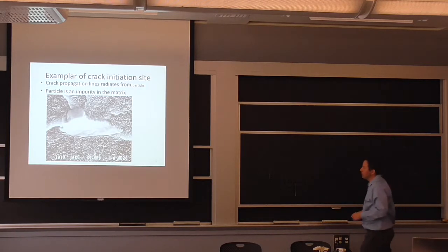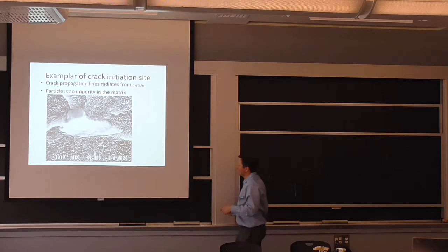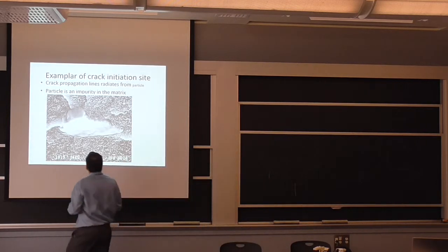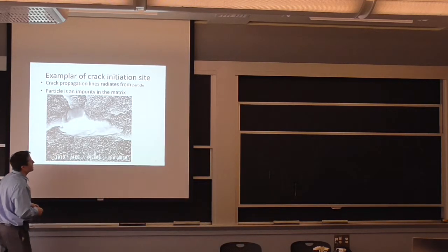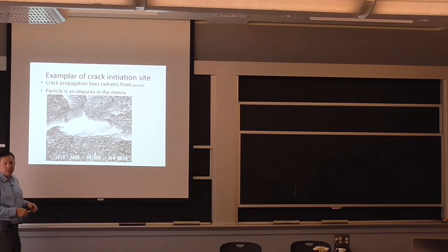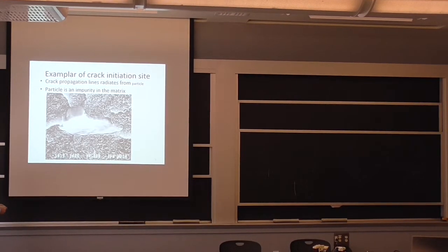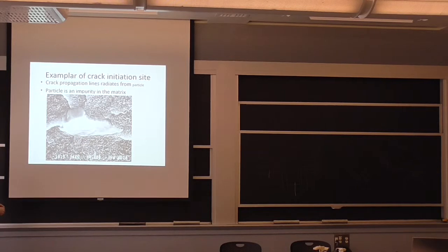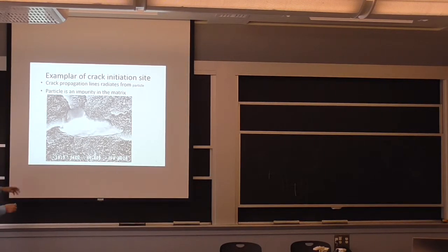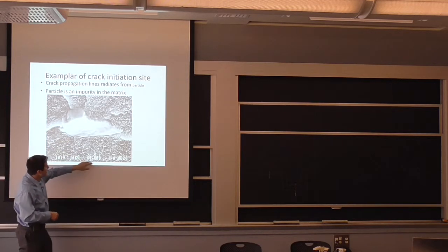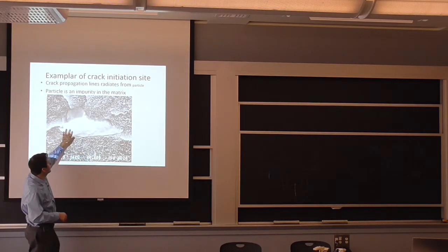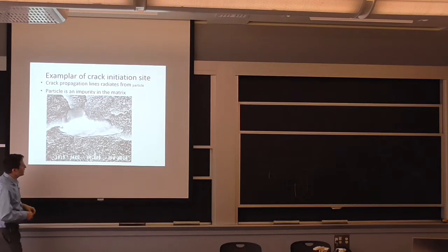And that, when we go to failure analysis later in my module, we'll go through more details about how to study the fracture and the cracking of materials. But here, essentially, there's enough evidence from looking at the entire specimen that the crack started at this point. The scale is 1 micrometer, so we're looking at a particle here that is of the order of 10, 15 micrometers in the entire section of the plastic.